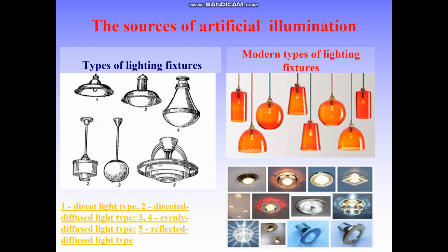The fluorescent lighting has certain advantages over filament lamps. Considering spectrum, they are close to the solar spectrum, give soft, scattered light without shadow, and have small brightness. Sometimes a small stroboscopic effect is observed, revealed as pulsation of light flux, which is considered a disadvantage of fluorescent lighting.